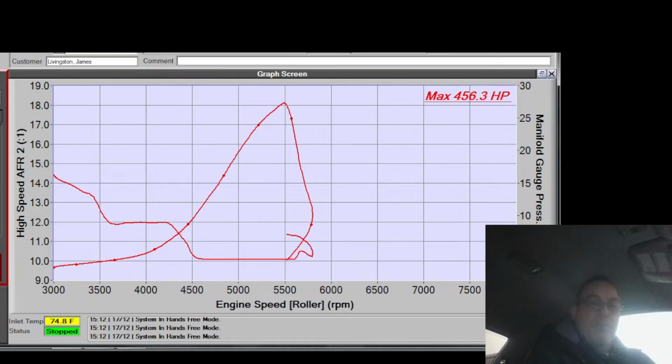It won't be available for combustion because it isn't mixed very well. It's a big glob, and big globs burn slow because a big glob has to burn from the outside in, and I've got to have oxygen get into there. Well, if I have this glob, we'll say this round circle, all these molecules of fuel, and I've got air around it, and I start to burn, well, it starts to burn on the outside, but then what happens is the byproducts of the combustion displace the oxygen that you need for the inner molecules.